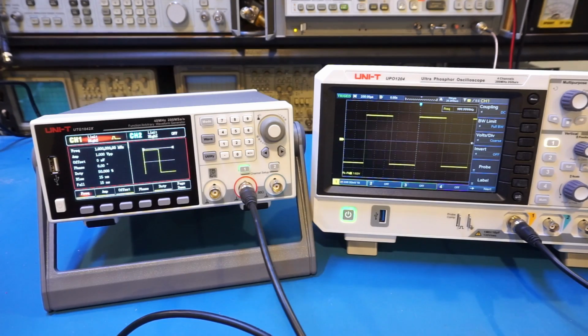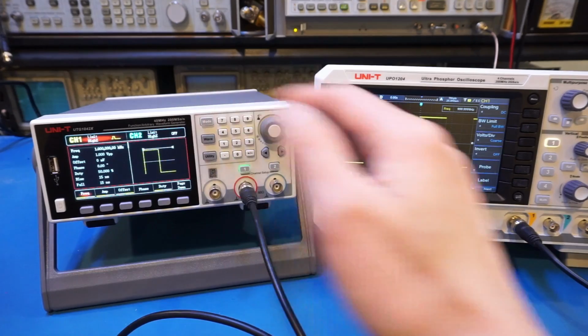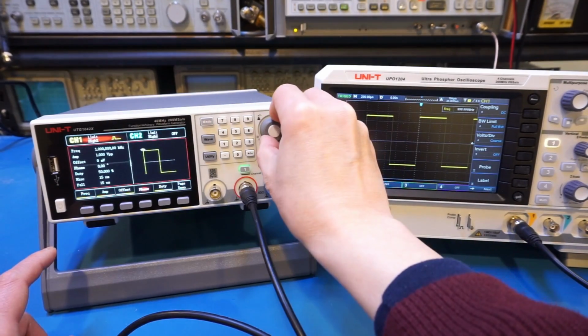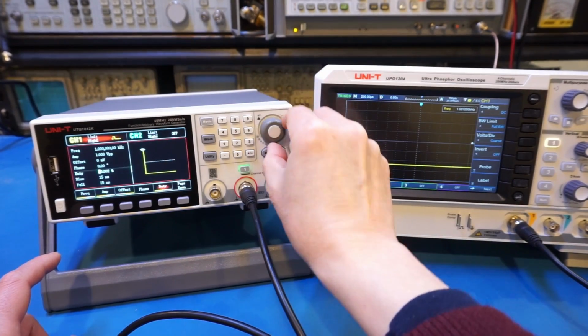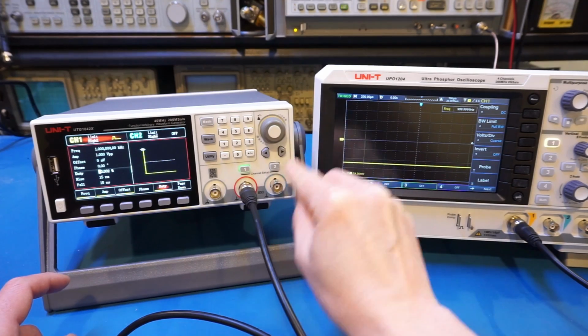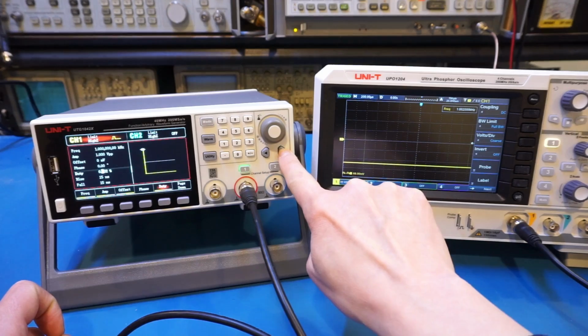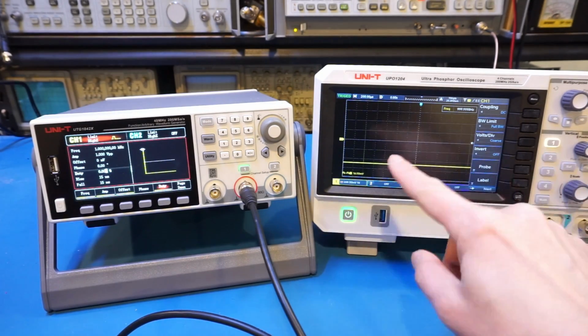And now we're looking at a 1 kilohertz pulse signal. For the pulse signal, we can actually change a couple more parameters. And let's actually take a look at the duty cycle here. So I can go down here and let's change the duty cycle to, say, oh, the shortest is actually 0.002%. That's actually quite nice. Let's see if we can get it any lower. Nope, 0.002 is the limit. So you can barely see the pulse here.